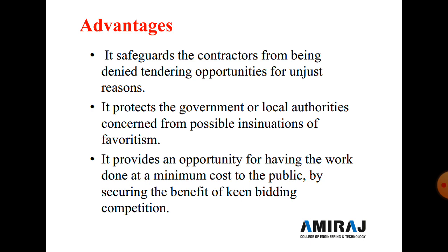Now here are some of the advantages of an open tender. It safeguards the contractor from being denied a tendering opportunity for unjust reasons, and it protects the government or local authority concerned from possible insinuation of favoritism, and it provides an opportunity for having the work done at a minimum cost to the public by securing the benefit of keen bidding competition.